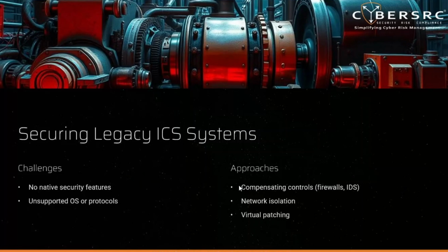First, no native security features. Legacy systems such as old server versions or an old PLC do not have any native security features because the security patches are not available anymore. So they are vulnerable to the latest security threats, unsupported OS or protocols, which is of course a threat that we have to solve. The OS is old, the protocols are old. We cannot implement new protocols because for that we have to upgrade the system, we have to stop the plant. That is not happening. So what will be our approaches?